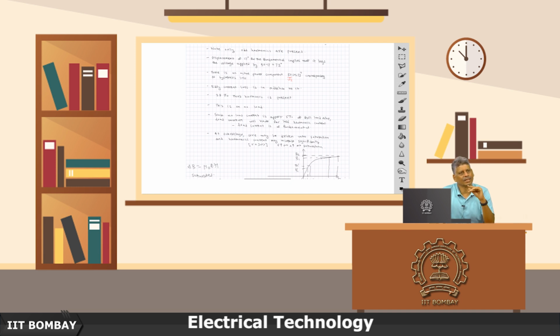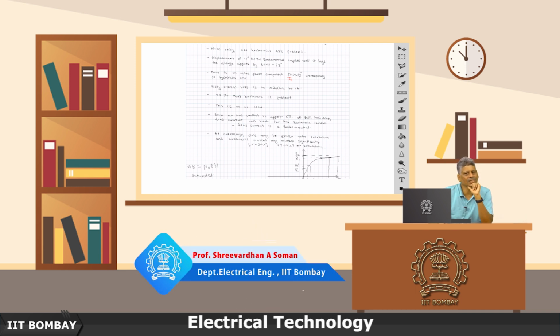That is why the grid voltages have to be kept, for so many reasons, insulation, overfluxing, so many reasons, within say plus minus 5% or something like that. We cannot allow too much deviation in the voltage, otherwise equipment, power apparatus will not function appropriately. So, we will